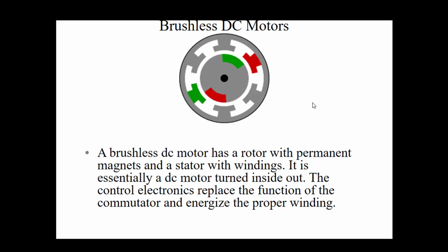So basically, it is identical to that rotating MMF produced by a three-phase machine stator winding. Similarly, here also we are giving a pulse. Now, unlike the pure sinusoidal wave, which is common in the case of a three-phase alternating current machine, here it may be a pulsating wave, because the inverter cannot produce a pure sine wave; that is difficult for the inverter.